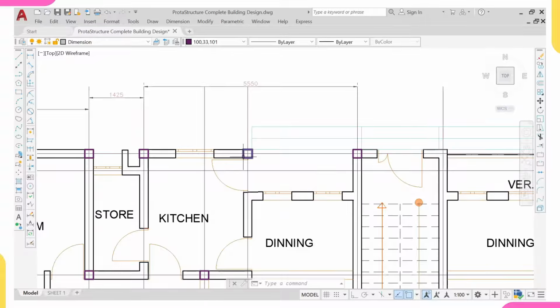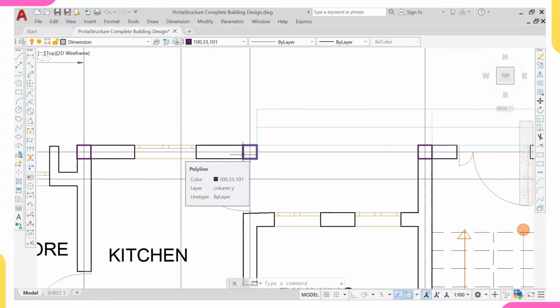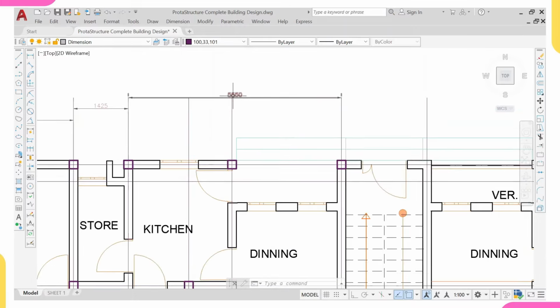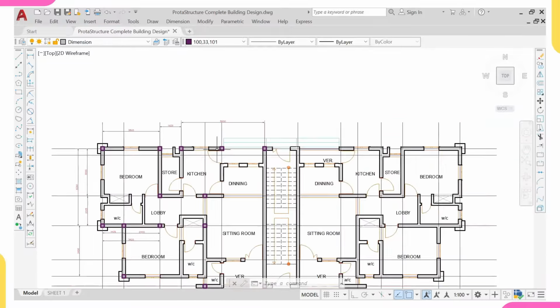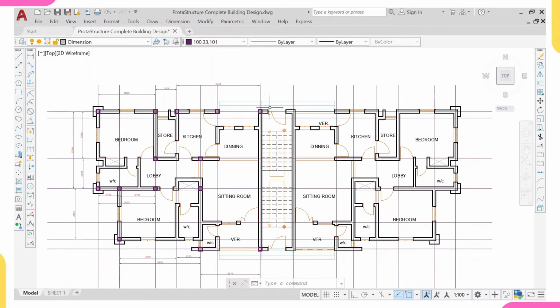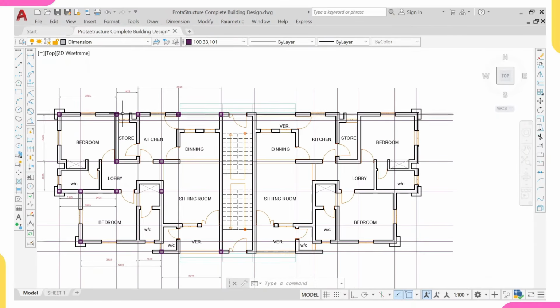You are still economical in your design because the cost of this column now, this is 4y16 and concrete. But if you remove it and just replace it with just one bar of y16 of 5.5 meter length, that means you save cost. But the client doesn't know, because all the work they have done is that maybe they will have a column here, maybe they will have a column here, here, and also in this case they'll have a column here, and here. They'll have columns placed all around the building.